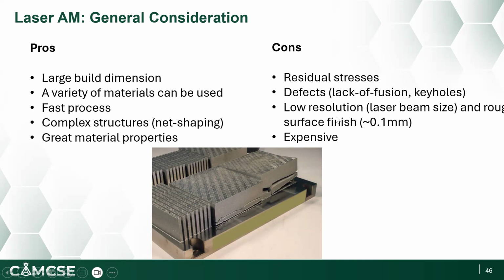We can only achieve hundreds of microns resolution and surface finish. If you need a better surface finish, you may still need to apply a post process. And one last thing is the process is expensive compared to conventional manufacturing, such as CNC machining, right?